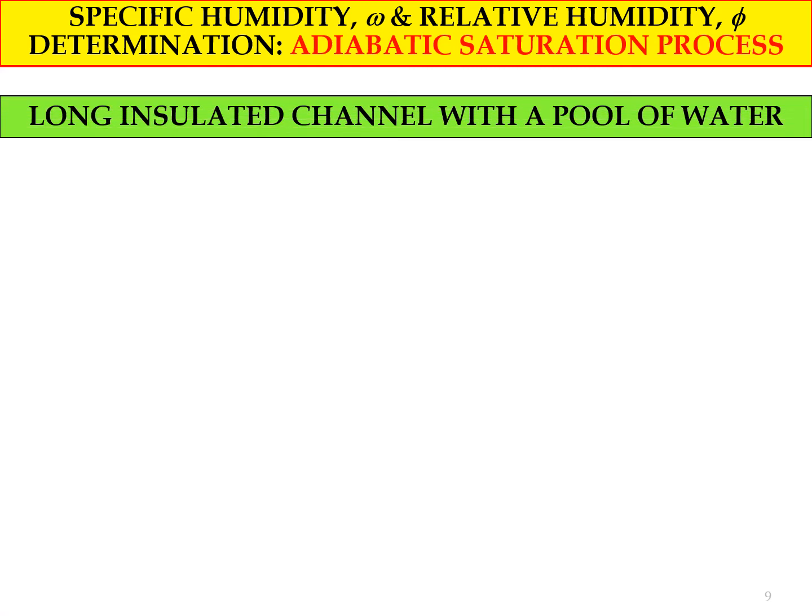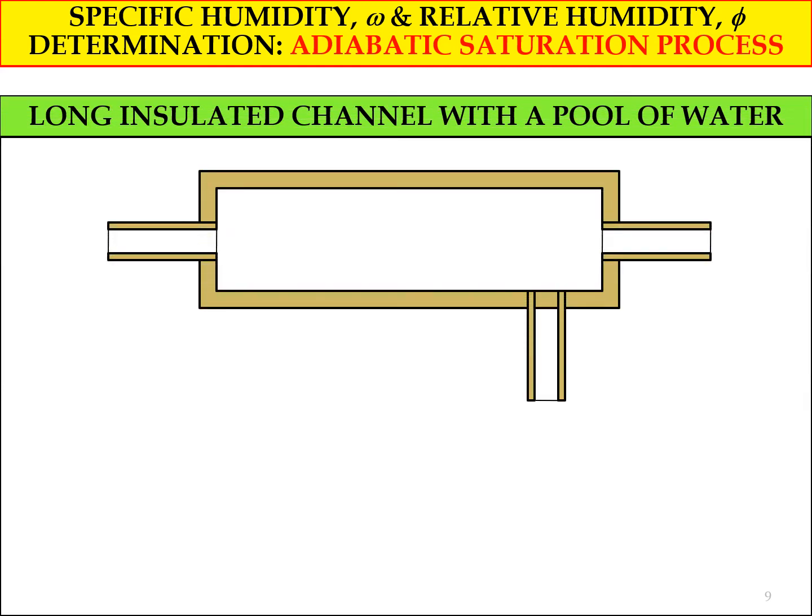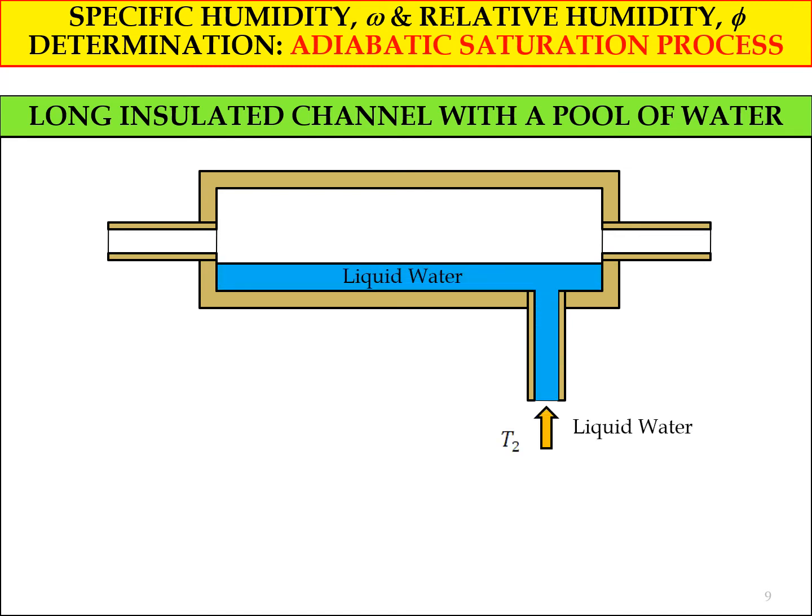Specific humidity and relative humidity determination, adiabatic saturation process. Okay, so this is the long insulated channel, and this is the pool of water, with the makeup water, which is liquid water at temperature T2. Let's say there is unsaturated air, or the environment air, at state 1 that goes into this long channel